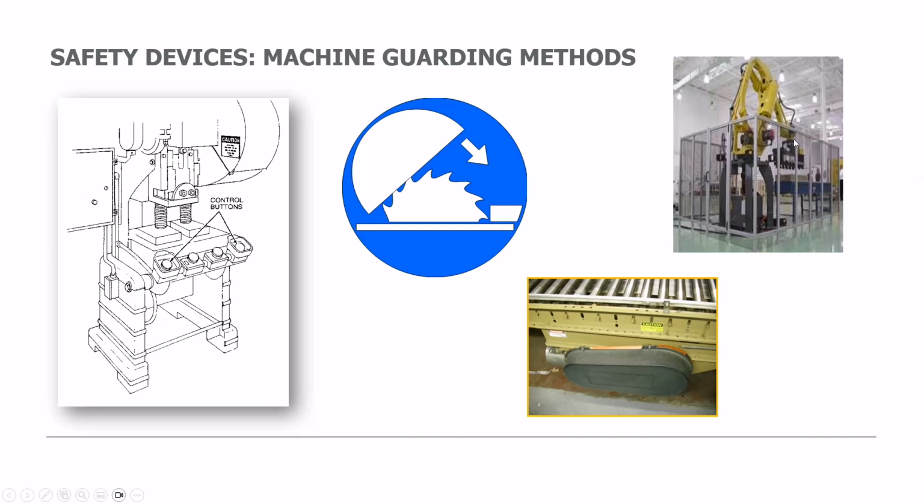This happens to be a robotic type of machine that you're going to find in some industries. But before you can go in there and do any type of work, it's actually affixed. The guard is to the outside of the gate area. In other words, when that gate opens, depends on how they've got it wired up, but basically as that gate opens, the machine shuts completely down. It's considered zero power going to that particular